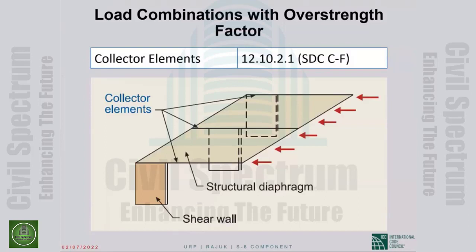Okay. Now let us explain that. So this is a slab acting as a diaphragm. A slab acted upon by lateral loads which will cause in-plane bending. So you are looking at compression on this face, tension on that face, and shears along the side faces. Those shears have to be transferred to supporting elements, shear walls or frames. Now, if that shear wall were